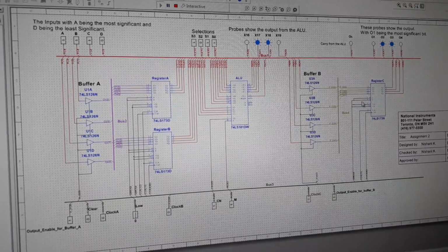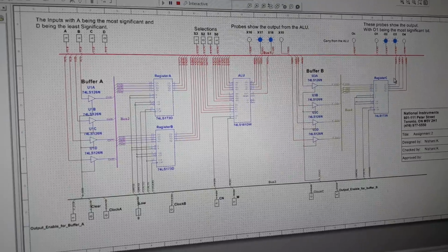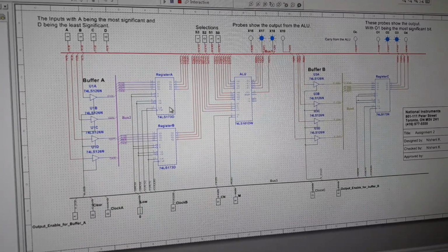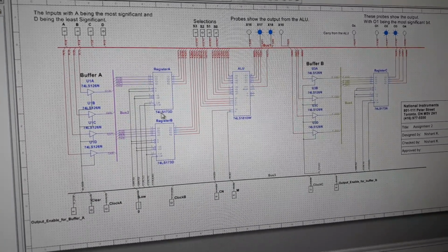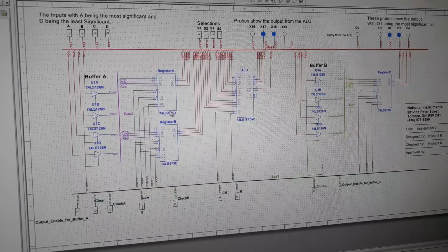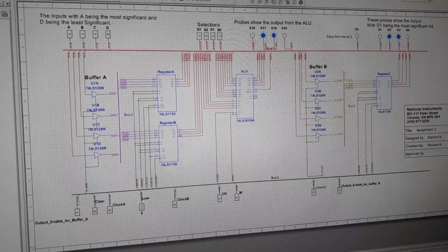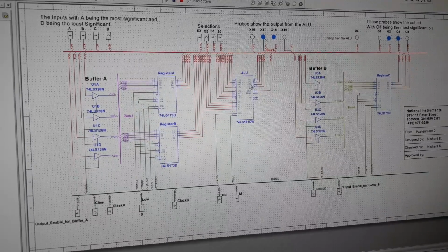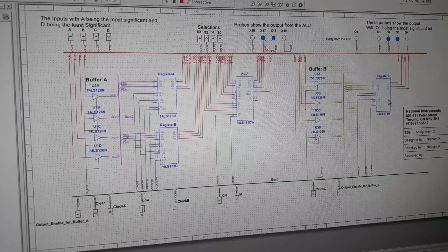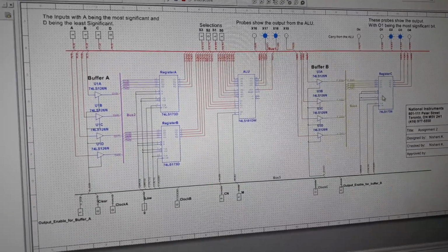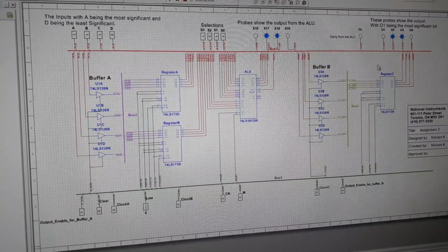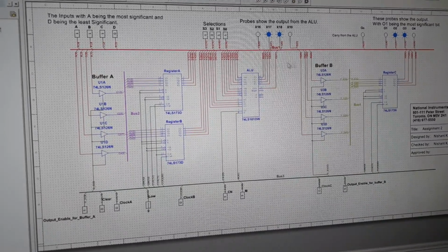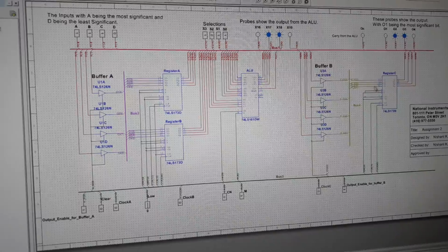And there's one note which I observed. As you can see, I'm using three registers, and two of them are D registers, and one of them is the N. When I was using the D register for the last operation, it was giving me some garbage values. So as a user, just be careful. Don't use register D for the final output. Just use the N one.